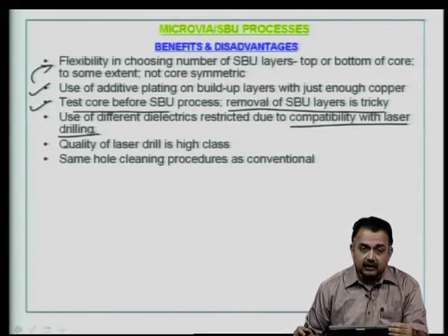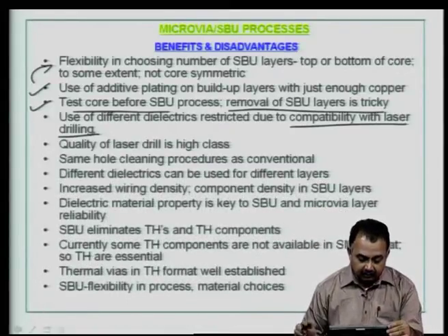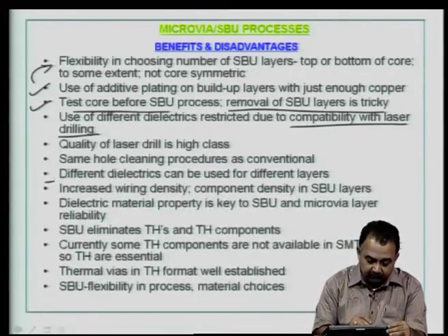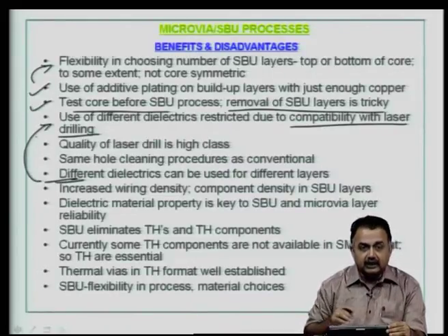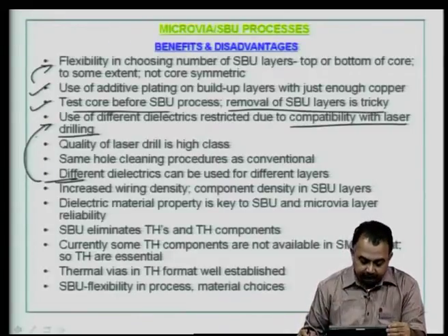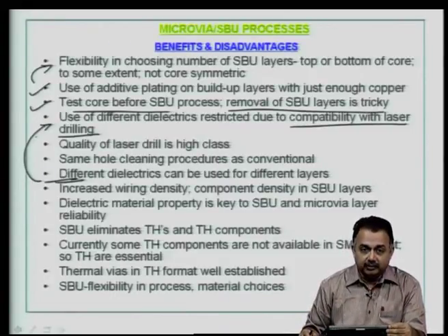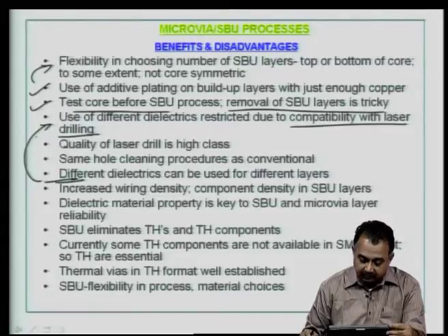Same hole cleaning procedures that we have seen in conventional are applied here. Different dielectrics can be used for different layers, but again try to link this issue with the statement that I have just mentioned. Increased wiring density obviously is guaranteed. Increased component density is also possible using this process.